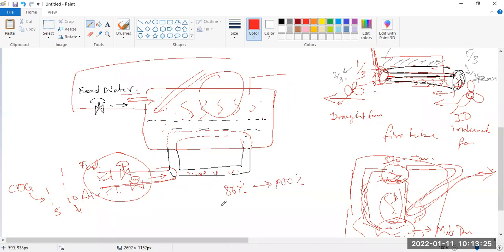If it is opening 80%, but feed water is very less, then all this water becomes steam very fast. Then we have to reduce it to say 50%, so that whatever water is available, we can make it steam, because the feed water ratio is very low.